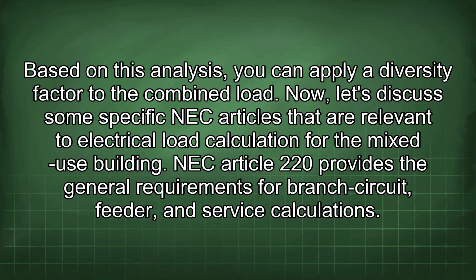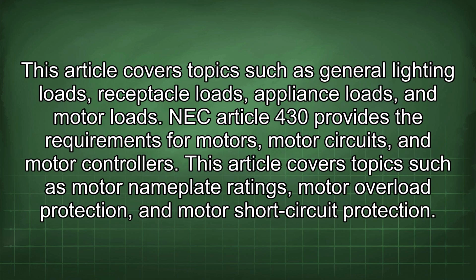NEC Article 220 provides the general requirements for branch circuit, feeder, and service calculations. This article covers topics such as general lighting loads, receptacle loads, appliance loads, and motor loads. NEC Article 430 provides the requirements for motors, motor circuits, and motor controllers. This article covers topics such as motor nameplate ratings, motor overload protection, and motor short circuit protection.